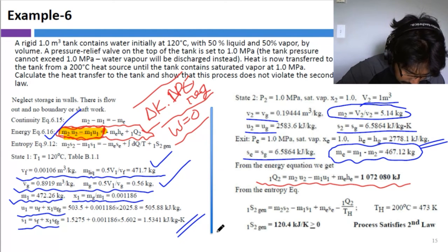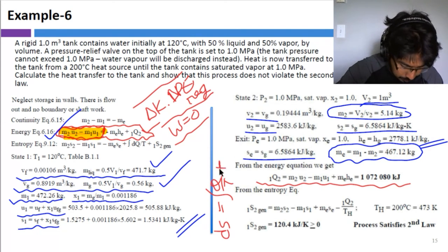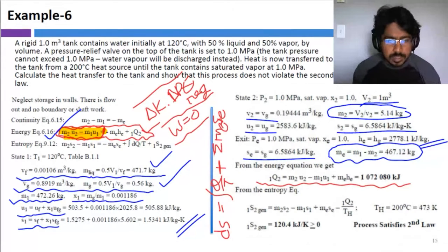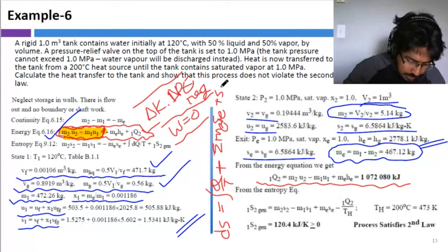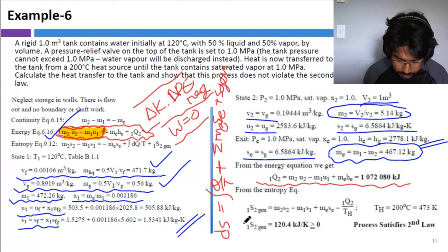So for this system, we can say that entropy change is equal to the entropy added by the heat transfer plus entropy left the system in the form of leaving mass, and we don't have any inlet mass coming into the system, therefore we don't have to worry about this, and then Sgen. And from this equation we can calculate the entropy generation component, right?